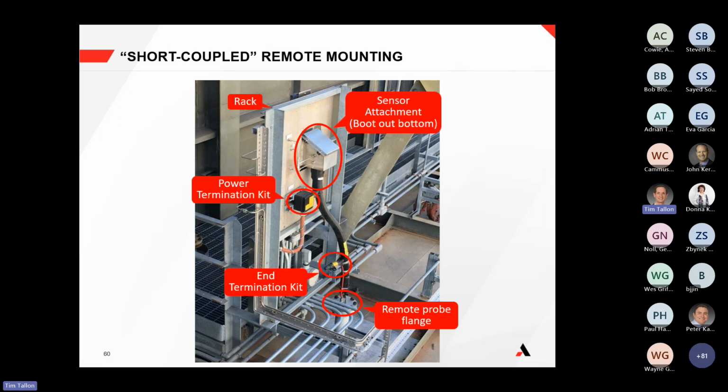I don't know if you want to comment on that at all, Joe, but aside from the 3/8 inch tubing, we like to have 2 tubes available for 2 reasons. One, because it's a return to process system. So if you wanted to return the sample back to the process, 2 tubes would allow you to always return it back to process. And then also, if you did not want to return it back to process, you would at least have a spare. If you wanted to vent it to atmosphere, you would at least have a spare that would always be available should the first one be plugged.